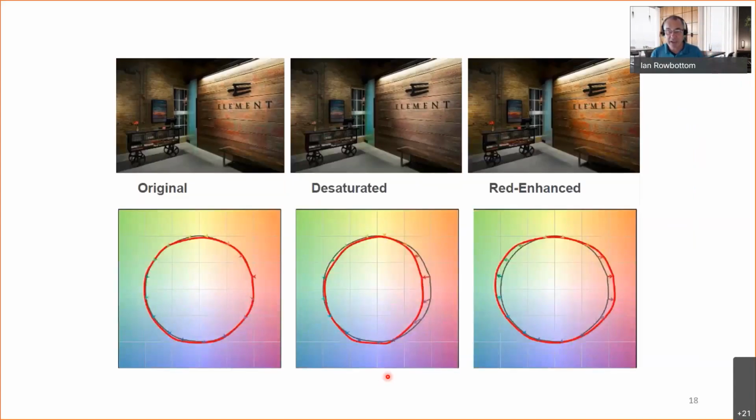Well, with the new metric, you get a pretty picture, these two circles. The dark circle in the background is called the reference. That is 100 CRI. So on my original light source, I'm slightly overdriving the blue, because as I come outside the circle, I am saturating certain colors. As I come inside, I am desaturating. So on the original, I'm slightly desaturating the green, yellow, and I'm slightly increasing the red.